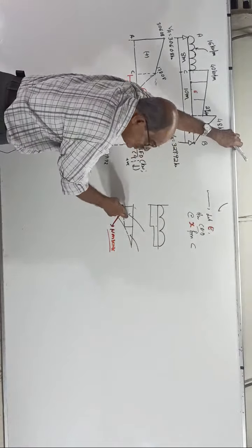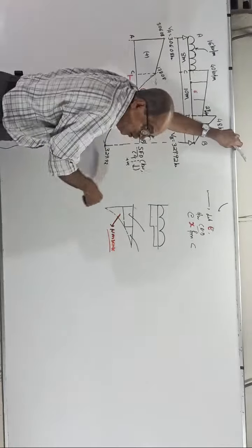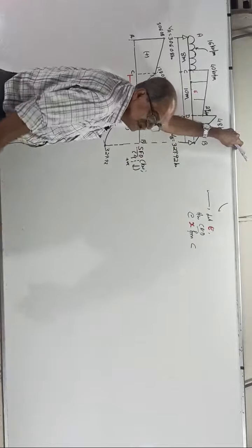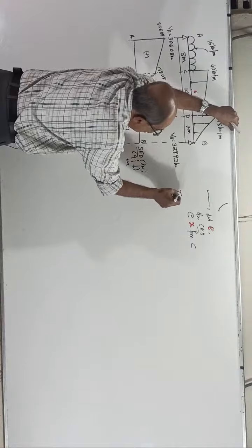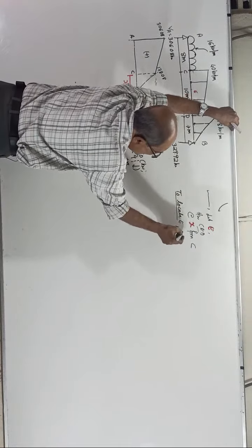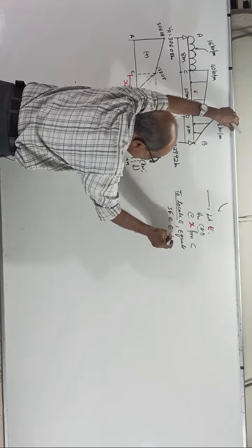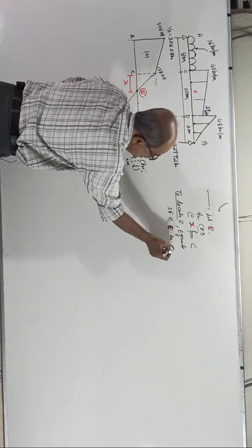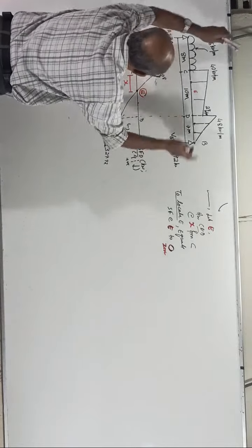They will tell you to divide into a rectangle and a parabola. No, you cannot do it. It is outrightly wrong. Therefore, you do not go for such things. Trapezium is trapezium. See, X from C. Now, to locate E, what you have to do is equate the shear force at E to 0.